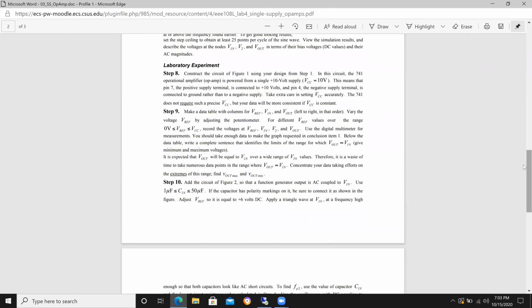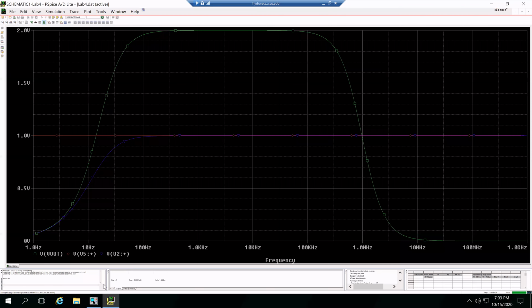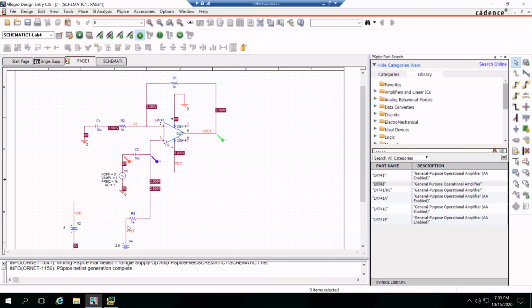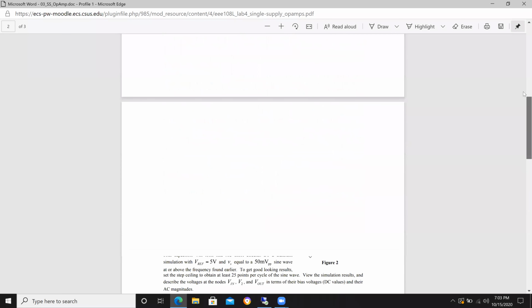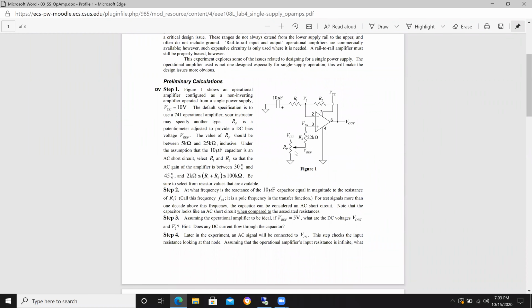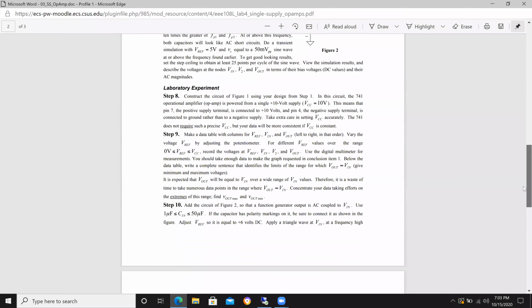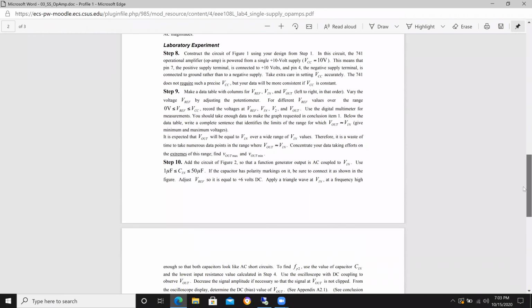For next week, you're going to build this circuit up on a breadboard. And the only difference is, instead of DC coupling like I did right here, your VREF through, this should really be a 22 kilo ohm resistor. I left it 1K, but that'd be your 22K right there. The difference with the breadboard is you're going to be building this circuit up with the potentiometer, then tuning the potentiometer in order to get the bias condition you want, the VREF.